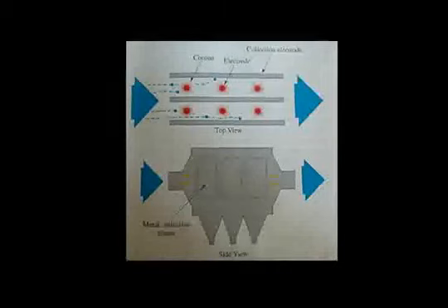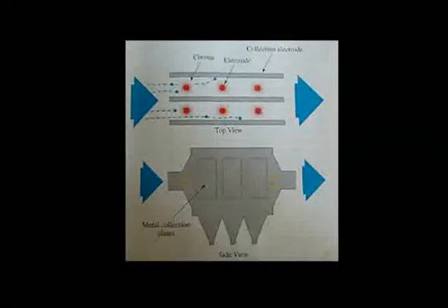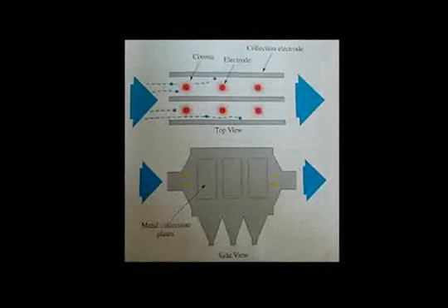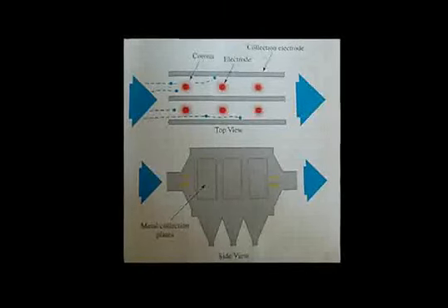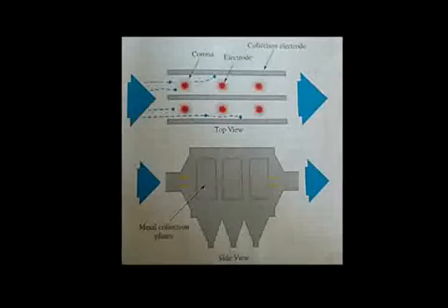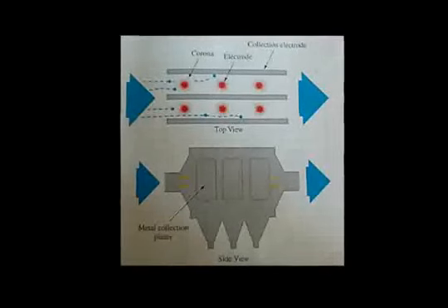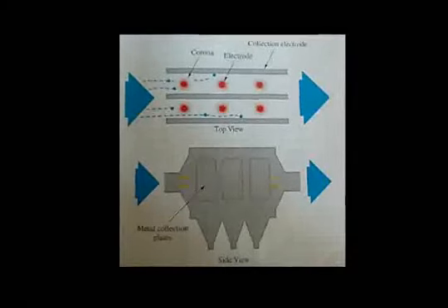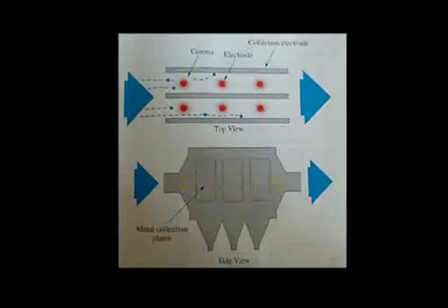The charging section can be designed in many different ways. It can be an assembly of parallel rods or wires, a screen pattern or bank of piping. Regardless of the physical design, the electrical principle is the same in all cases. Figure 1-11 illustrates the operation of the electrostatic precipitator.